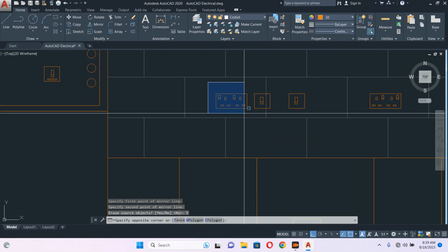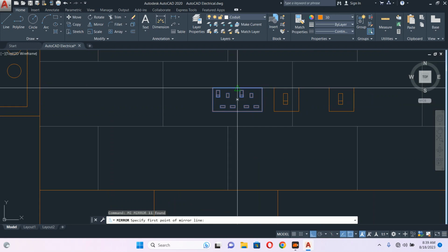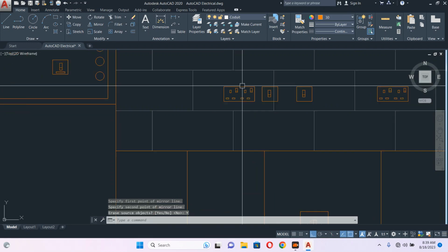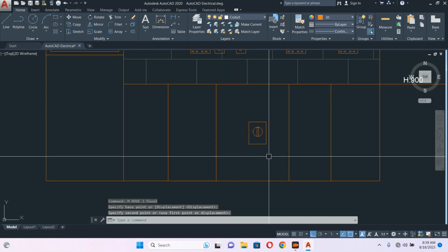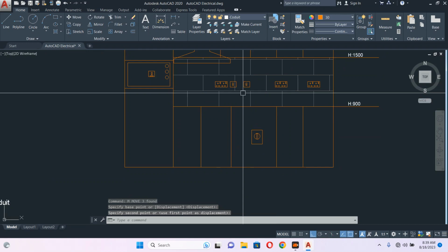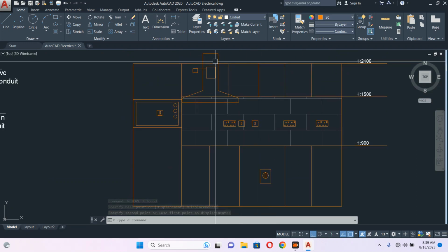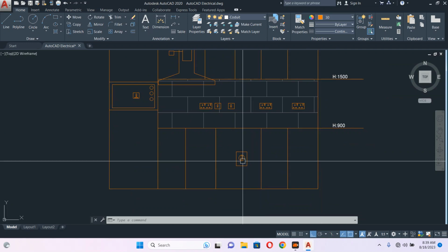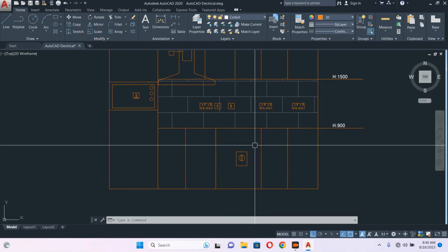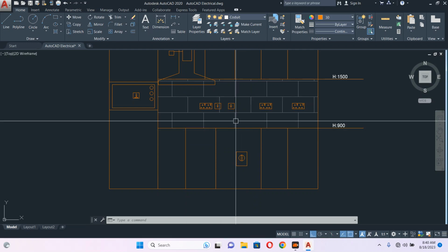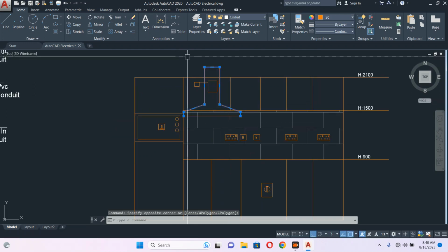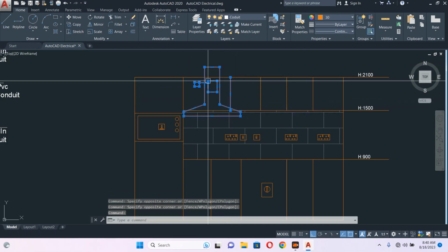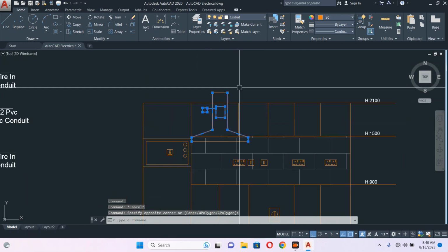So in that case you have to raise an RFI. What is RFI? Request for information. For example, we have an issue like this: we cannot provide this outlet here, it will affect here, so what is the solution? The consultant will discuss with the architectural people, and they will move this cooker and provide what we have to do. This RFI is not only for problems, you will raise it not only for a problem. If you don't have any information in the IFC,